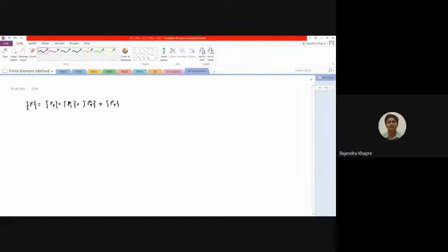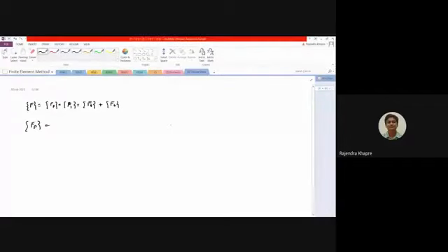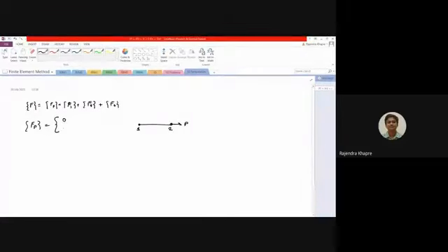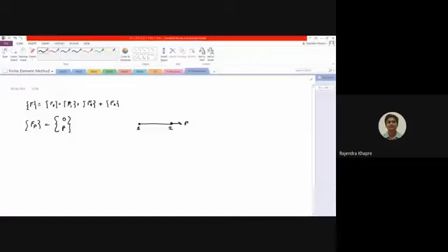So we have already seen, if it is a point load. If you have a problem which is something like this, and there is a load acting at this point, let us say this is node number 1 and this is node number 2. What we generally do, if it is acting in the direction of the axis, at node number 1 there is no force, so we consider this as 0, and at node number 2 we consider this as P. So whatever values are there, you have to substitute in the force matrix, that is the local force matrix, as the direct values.